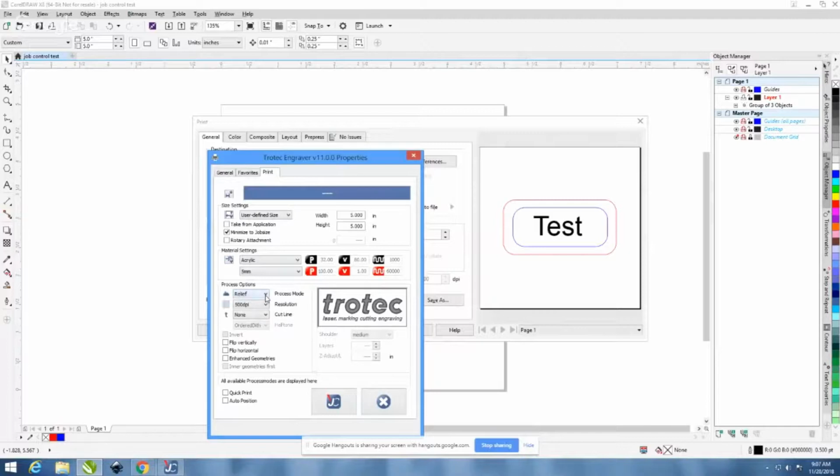Yeah, go ahead, Anthony. So next, we got our layer mode. I'll let John explain this one as well for you guys. Yeah, layer mode is similar to relief mode, but instead of doing the job once and varying the laser power on the fly, it actually breaks the job up into multiple layers. So in this case here, we have layers selected at 12. We'll actually break the job up and engrave it 12 times, but the darker dots will get engraved all 12 times, and the lightest dots may only get engraved once. So you get a more extreme 3D effect, but it isn't as smooth as relief mode, and it takes obviously 12 times longer because you're doing it 12 times.